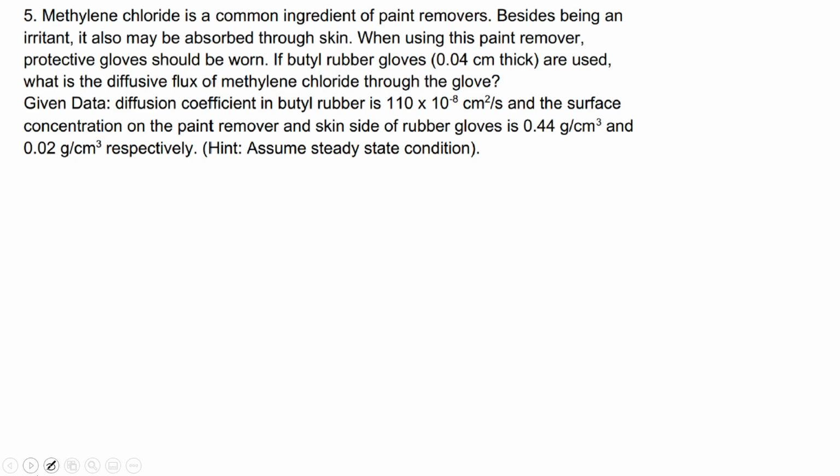Okay, so the question is: methylene chloride is a common ingredient of paint removers. Besides being an irritant, it may also be absorbed through skin. When using this paint remover, protective gloves should be worn. If butyl rubber gloves are used, what is the diffusive flux of methylene chloride through the glove? The diffusion coefficient is given, and the surface concentrations on the paint remover side and the skin side of the glove are given respectively, and you have to assume a steady state condition.